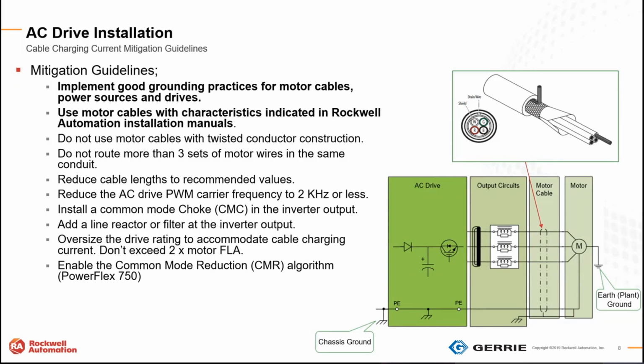So it's just, hey, no more than 3 sets in the same conduit, and we can hopefully eliminate some of that capacitance coupling. Reduce cable lengths. That's a hard one to do. It's a physical requirement typically of the installation. But if we can keep the drive as close to the motor as possible, that's always a good thing.